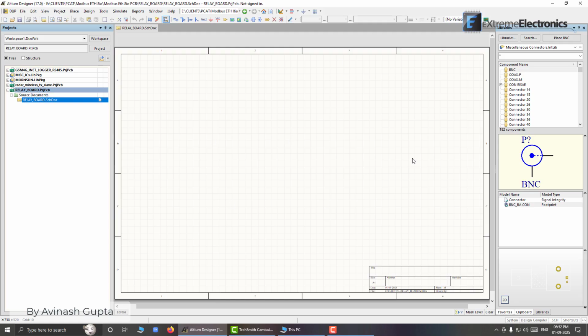And now here is our sheet, the schematic sheet, and this looks familiar. We have some grid-like patterns, and we can see the grid over here. These are 10 units wide squares, so the length is also 10 and this is also 10. In a schematic it does not matter what the unit of this grid is, but it will matter when we move to the PCB. So it is kind of a logical unit, 10 units, okay.